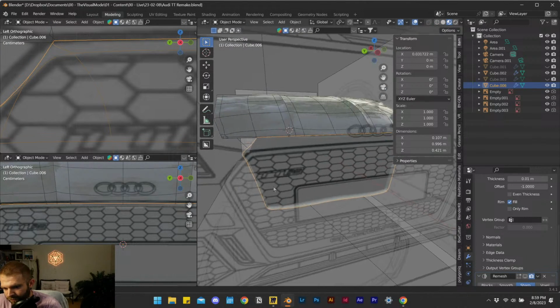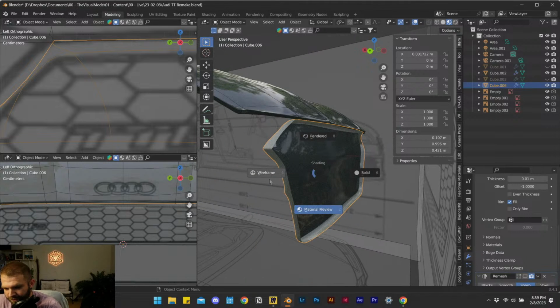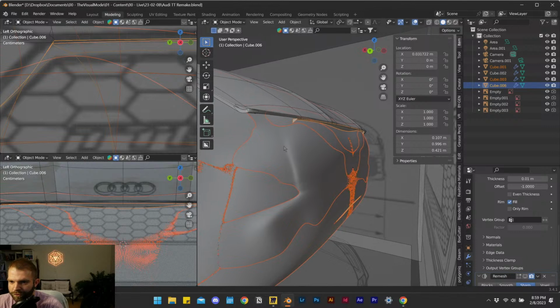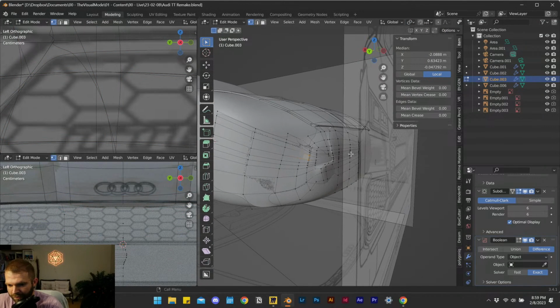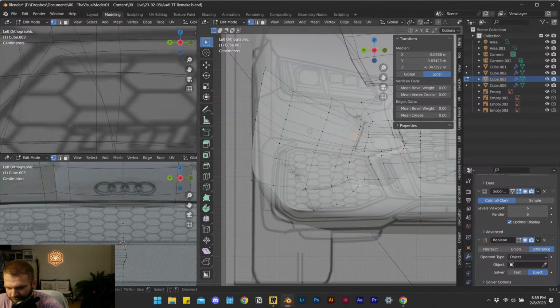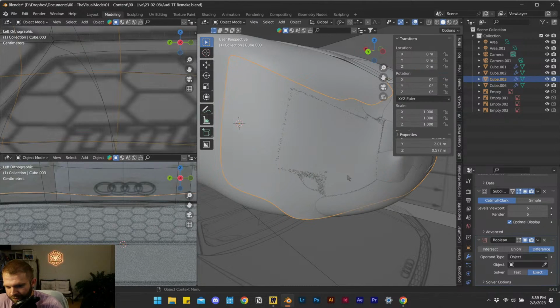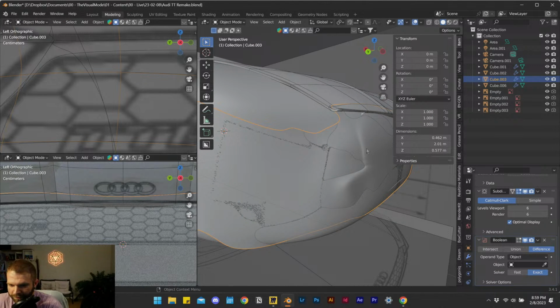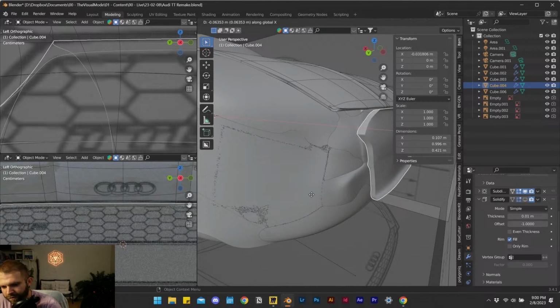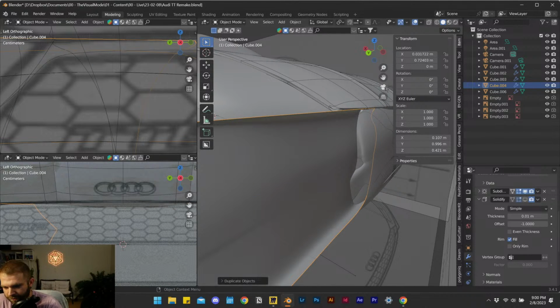All right, so that's how we start adding a bit more detail. This can obviously take many levels. We go in over here and we select the main body of the car. We can now select the singular set of faces for this whole situation here, which is like another grill piece. Or if I wanted to just keep and build around that, I could select the face that I had just worked on, copy that over with Shift D, and then from the front view,